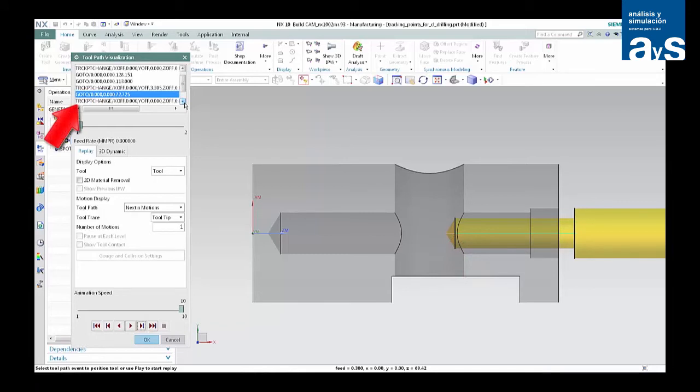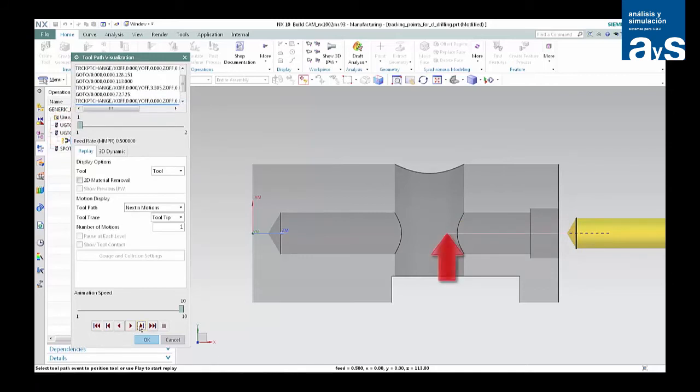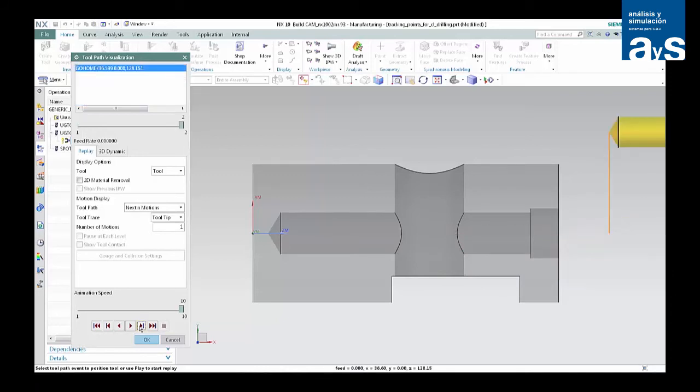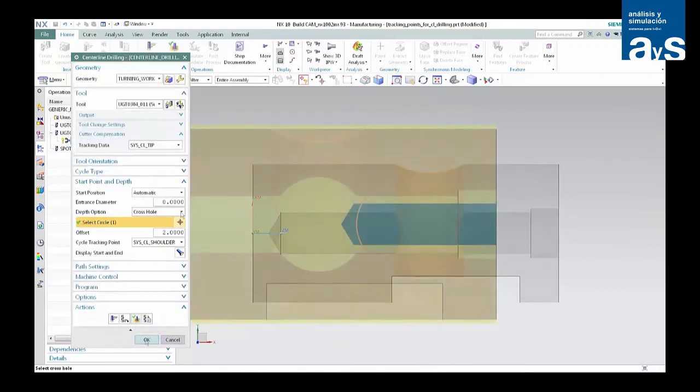Another tracking point change is indicated, this time from the shoulder, used for drilling cycle, to the tip, used for non-cutting. Click Step again, and notice how the retract move uses the tracking point at the tip of the tool for non-cutting moves. Click Step 2 more times to complete the tool path. The non-cutting moves continue to use the tracking point at the tip of the tool.